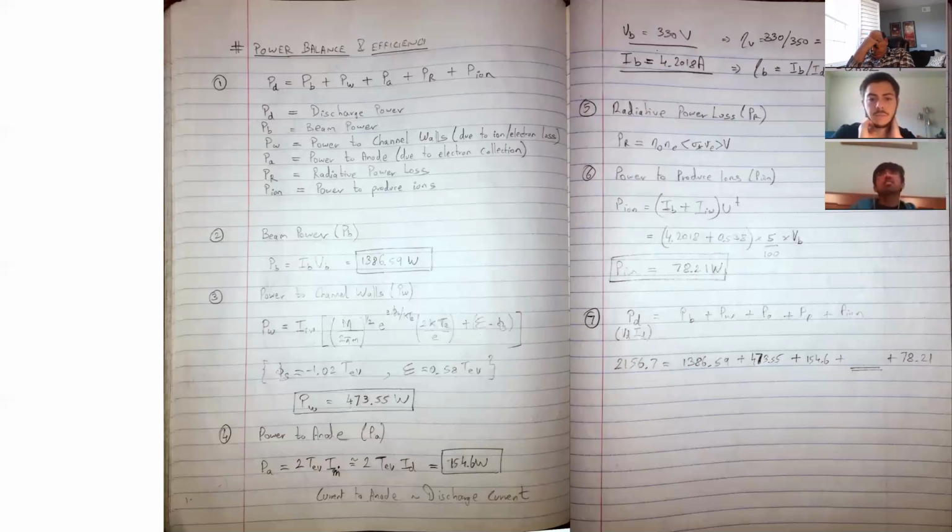So I think there are a few things. The first point is it's a 2.2 kilowatt thruster, so the amount of power input is not more than 2,200 watt, out of which we are able to extract 1386 or 1400 watts. So that's the efficiency: 1386 divided by 2000, something like 40% efficiency. Yeah, Hall thrusters operate at about 50% overall efficiency, and the rest is losses of various kinds.